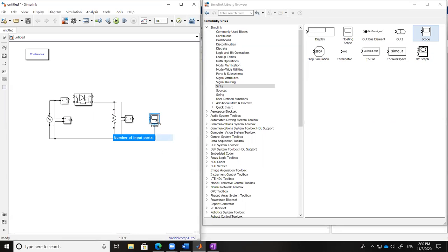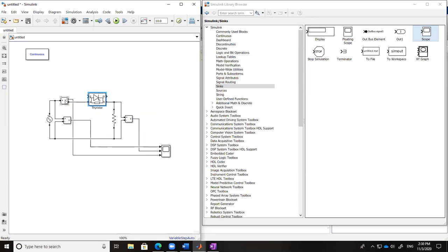Okay. So I will bring a scope here and there will be 3 terminals, right? The first 2 terminals will be connected to voltage, output voltage, right? And then we also have the current. The current is the same in the line. So I'm not going to connect a separate load current and separate source current. That is not possible here. So now I have all the quantities available.